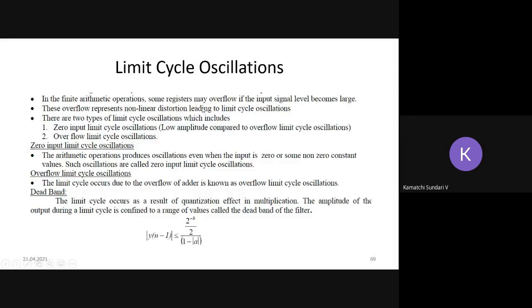For example, I am trying to explain the overflow concept. If I am adding two numbers, for example, in the decimal system, 5 plus 3, right? I need locations to store my data 5 and 3. One location is used to store my first input 5, and the second is used to store my data 3. And I have a register to store my output, the summation output. In that case, 5 plus 3 is 8, so my result can easily be accommodated in my register.